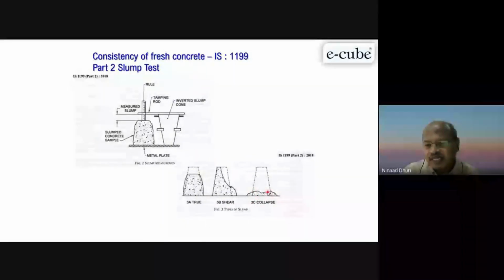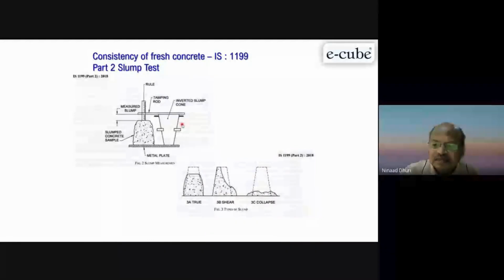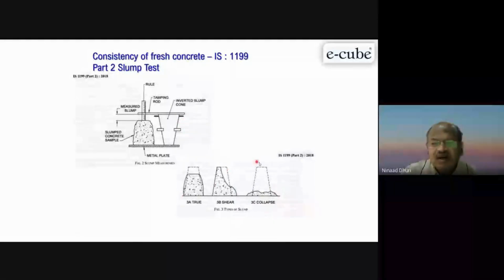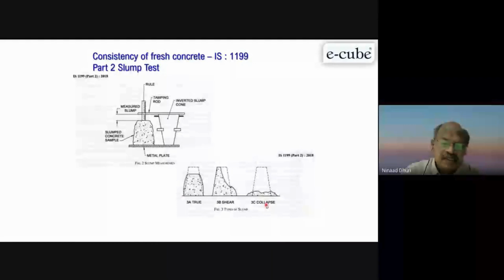Now, once you get this level of slump, this test is not applicable. Then we have to go for another test. But when you are designing concrete in the laboratory, slump is a very good indication about the quality of your mix.